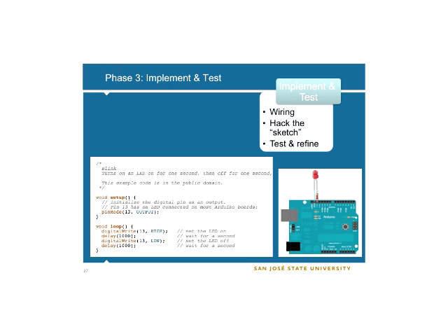And then the next stage, step 3, is to get a little bit more technical. The logic here is very simple, sort of a hello world. It makes an LED blink for 1 second and then off for 1 second. These are basically all the lines of code that you would download and install using the IDE. And this is the wiring diagram for this circuit. You've got an LED and a resistor connected right to the Arduino system.